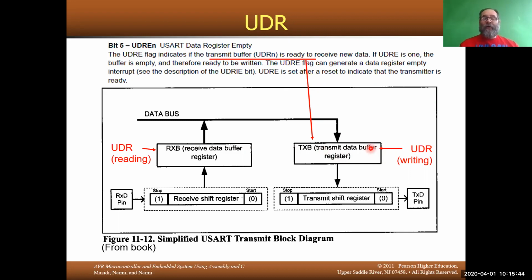Now, if you tie this to an interrupt, probably before the first bit of this character in the shift register is shifted out, you will have loaded the next character to be transmitted into the data buffer register, or into UDR0. And if you think this is difficult to understand, think about the poor slobs that had to design the hardware. Some truly impressive stuff that they did.